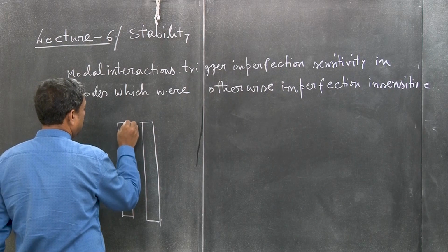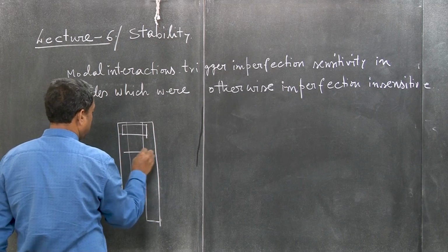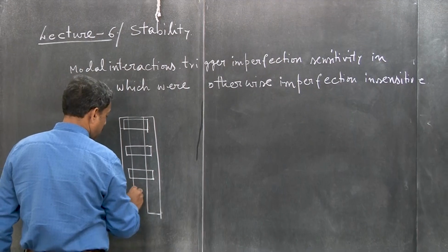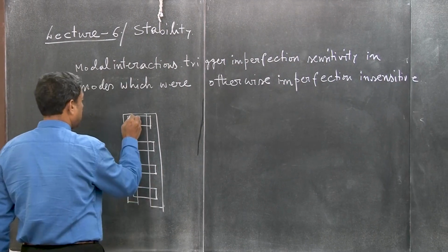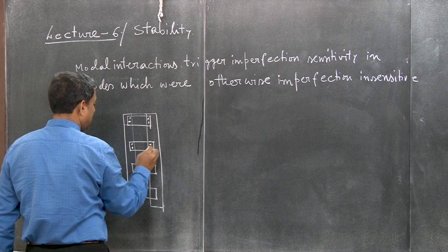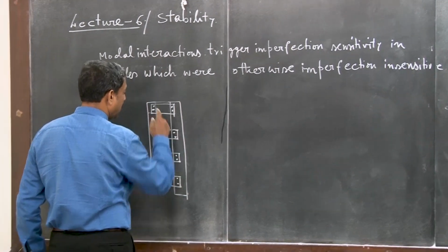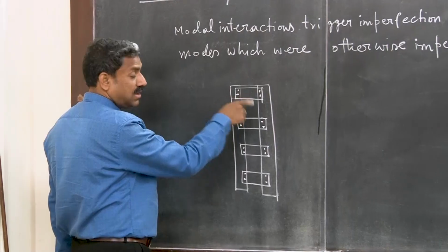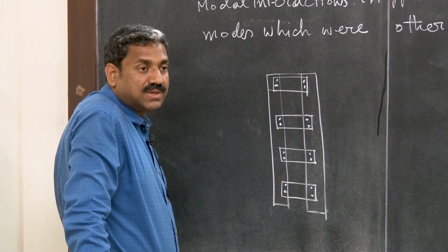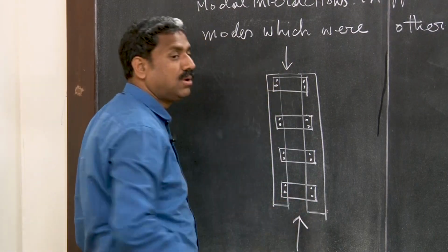These columns are connected, or reticulated, by this batten system, right? Either they are welded or bolted, right? This is batten plate, right? So these are maybe two different angle or channel sections which are connected, and why they are battened, because you want to use them as a single unit, right. So, when it is subjected to buckling load, what kind of mode will be there?